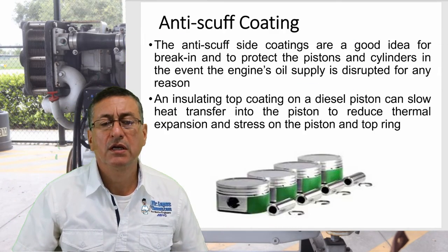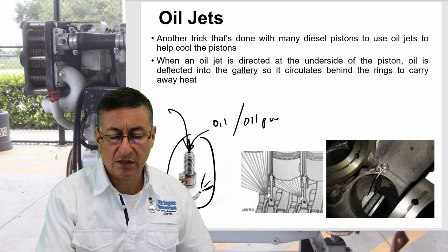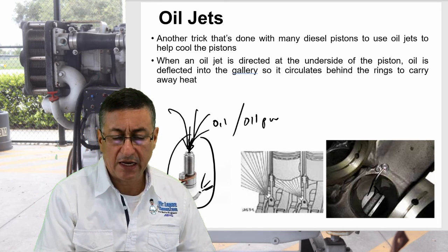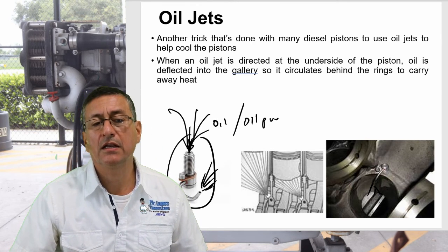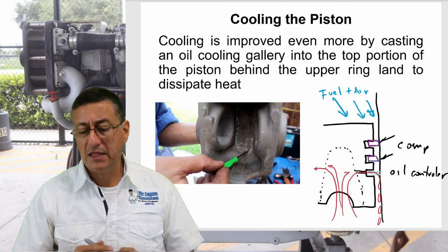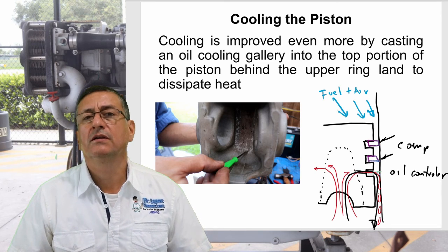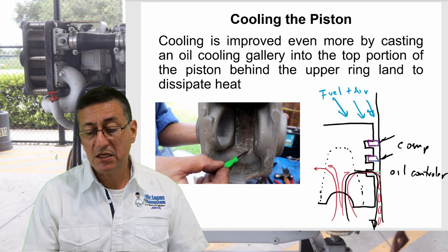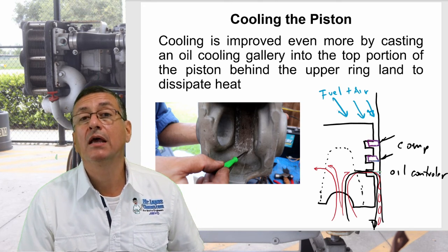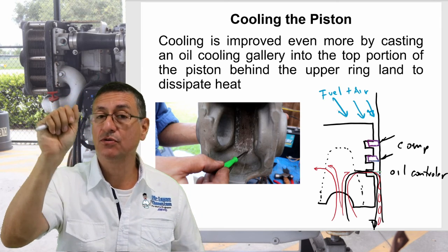In other words, the function of the oil jets is to introduce the oil on top and spray the oil on the bottom of the cylinder liner, and at the end of the day the oil enters here, goes over there, and returns. This is the path of circulation of oil. If you check this picture, we have oil until the bottom ring, the piston ring.